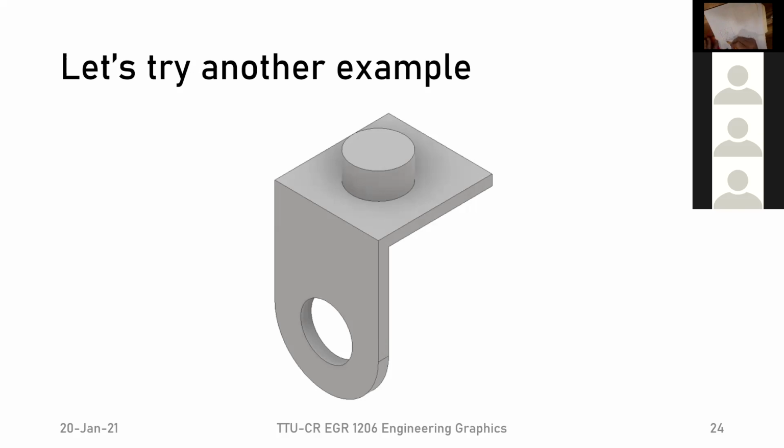These four lines make a cylinder just like these four lines make a cylinder. Doesn't matter if they're hidden lines or not, they're still a cylinder. Now for these ones, it's going to be tricky because the center dash is going to be very short. Like that, and then the same here, right? Because again, this hole is a circle. So we'll do a small one right there, there, and there. So that's what we get.